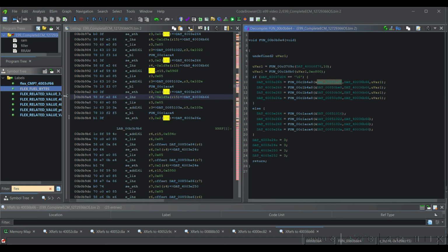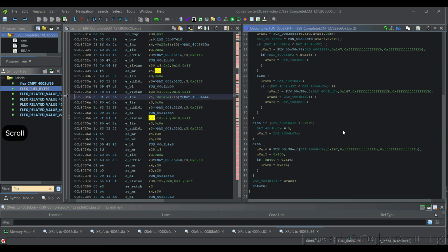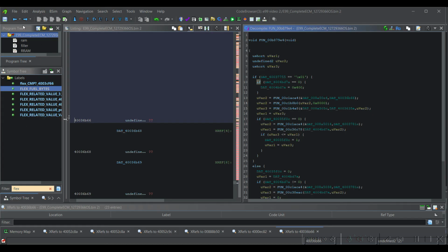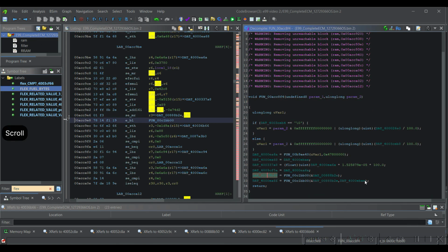You're just going to have to start tracking. If you want to know about this flex fuel stuff, you're going to have to start tracking the values found in those 3 functions that reference that set of bytes. And you're going to need to figure out what tables they play a role in, and eventually you'll have a good idea if it's affecting your fuel strategy and how exactly.